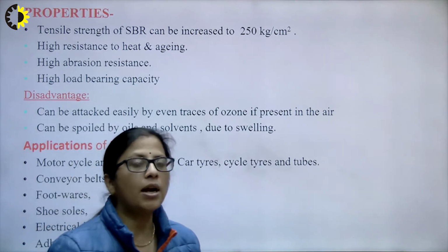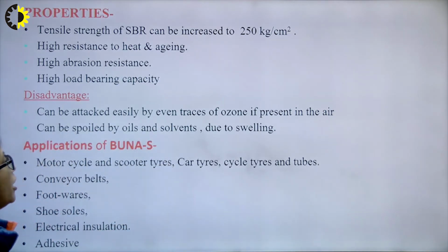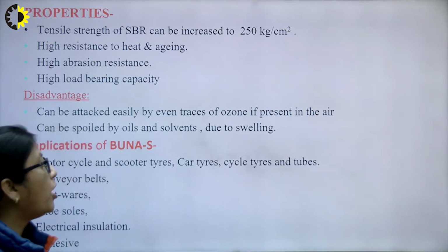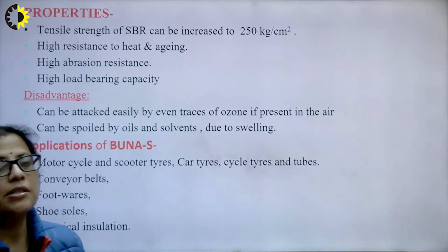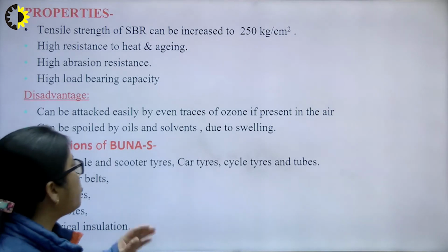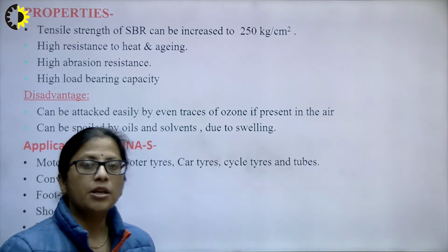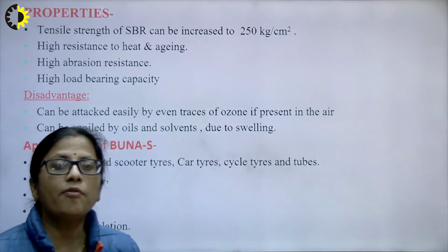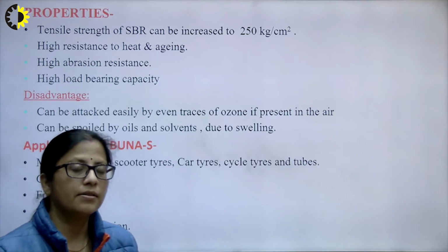Coming to the disadvantages of Buna S, this molecule can be easily attacked by ozone even in the presence of air. And Buna S can be spoiled by oil and solvents because it has a tendency to get swelled up in the presence of oil and different solvents.